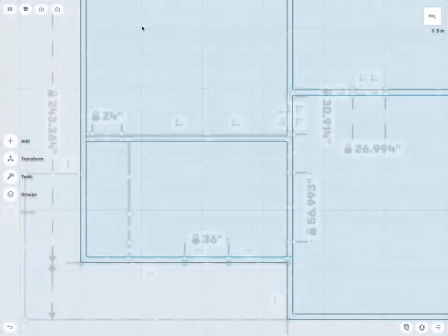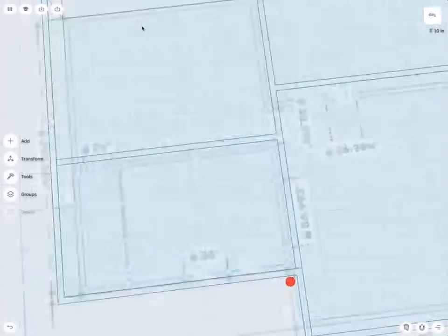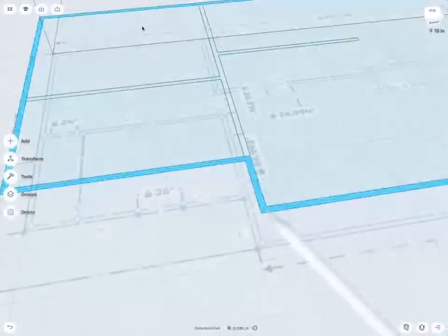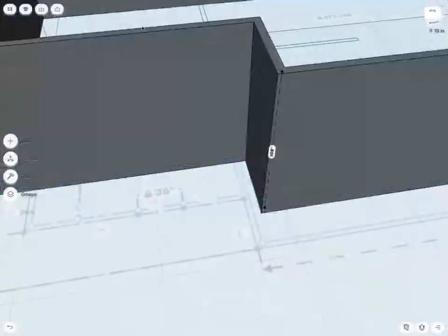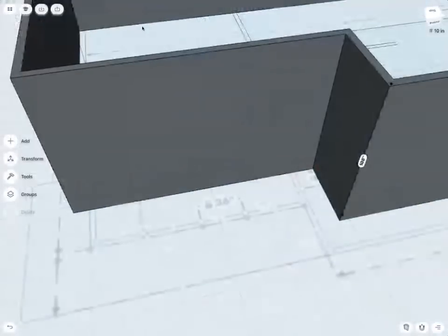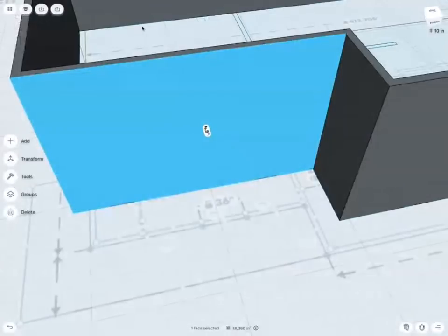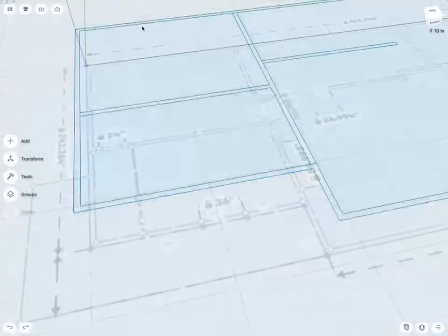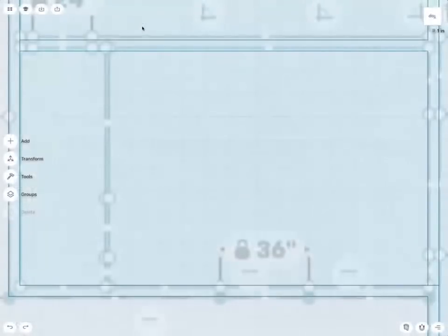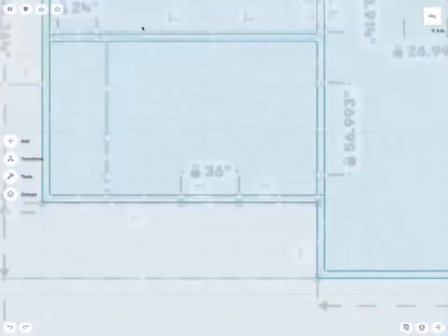So there are multiple ways we can create, for example, the doors. We can draft up the walls. That means I select, for example, this fill, then I sketch up the wall, and then I select this face, move to it, draw the outline of a door, and then cut it out. That's one way. I use that primarily for windows. I find that's a lot easier when we simply follow standard architectural drafting practice.